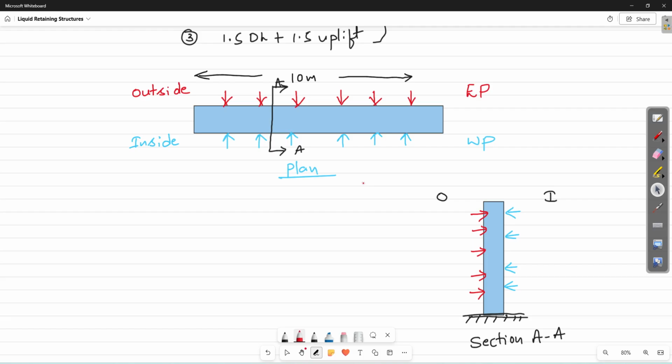So here you have two types of bending. One is M11 bending and the other is M22 bending. M22 is vertical bending, M11 is horizontal bending. In case of horizontal bending, here you have a connection. This wall is connected to some other wall. Again, on the right side also, this edge is connected to some other wall. So there will be a minor fixity, not fully fixed.